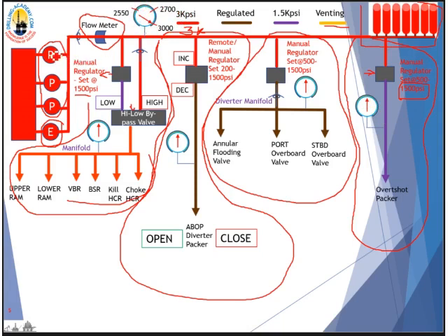Then the primary pumps will kick in if the pressure drops to 2,700 psi, which is a 10% drop from 3,000 psi. If the pressure in the main line continues to drop to 85%, which is 2,550 psi, then the secondary pump will kick in and charge the system up to 3,000 psi, and the pressure in that corresponding line will also be charged up.